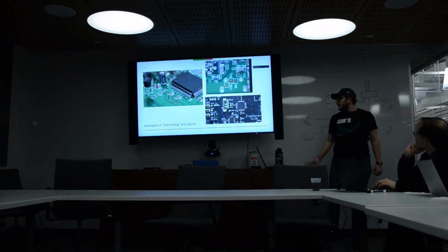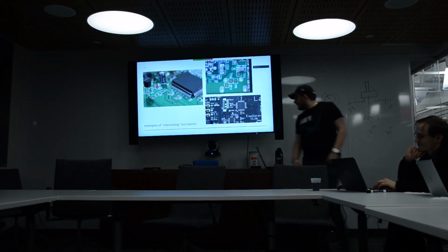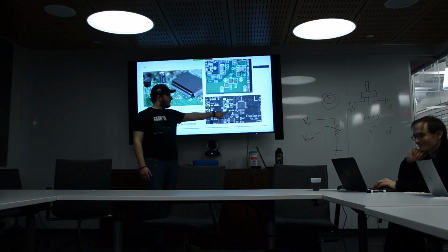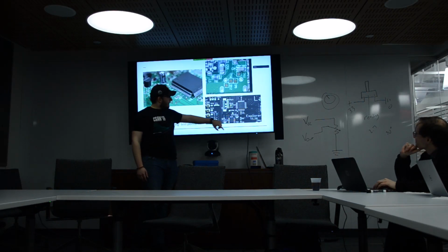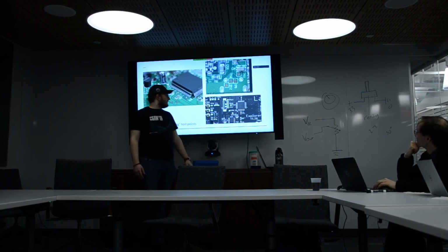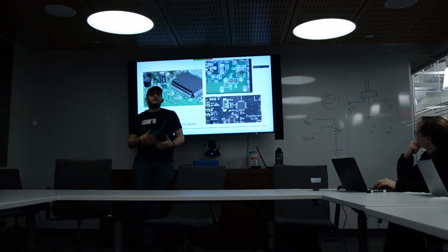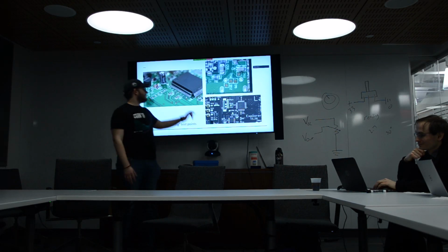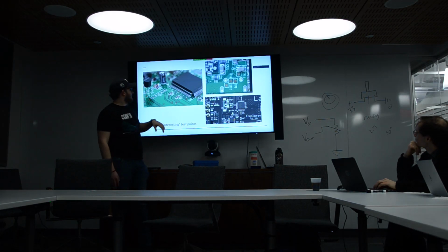These are a couple of examples of everything I just talked about. So all of these gold circles that you can see here, so on the bottom right one, the one that's labeled TP9 for example, that is a test point that they were using during manufacturing and during device development to make sure that when they were sending signals around the board, the signal that they thought they were sending was actually getting sent. These are, and I'll explain why they're useful in a second.